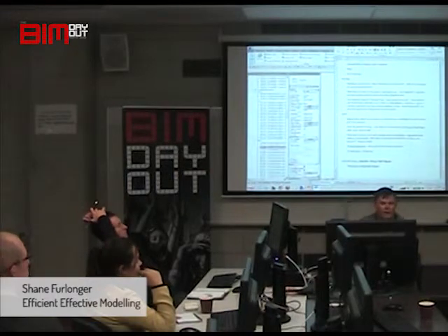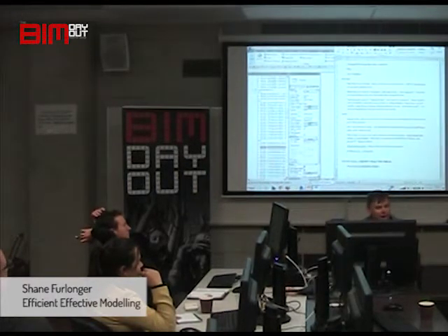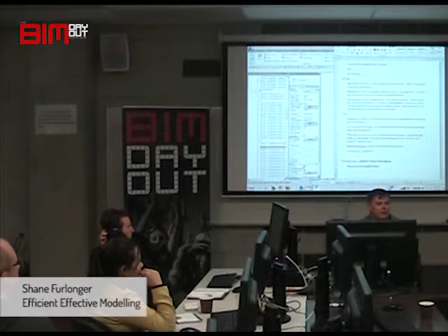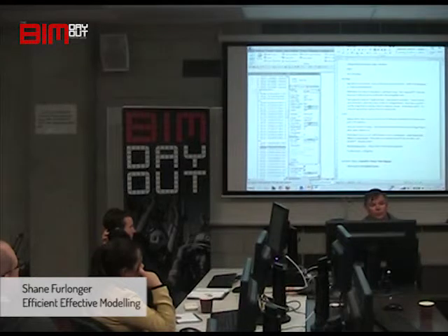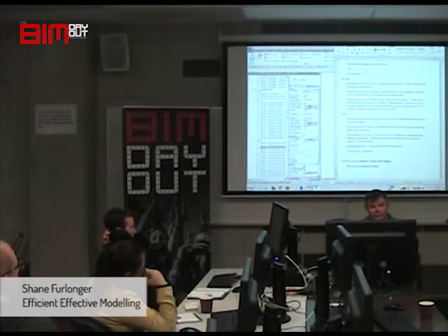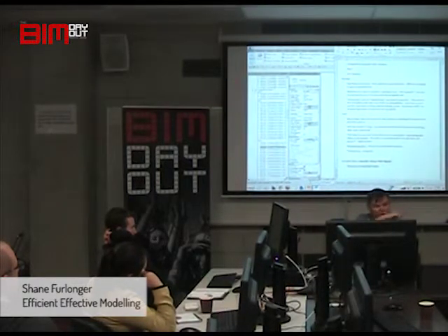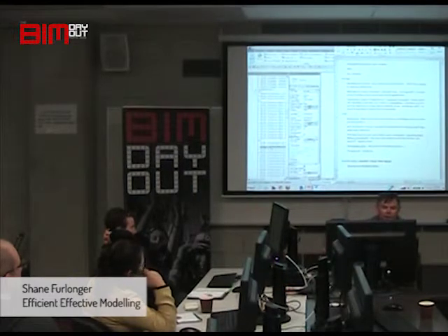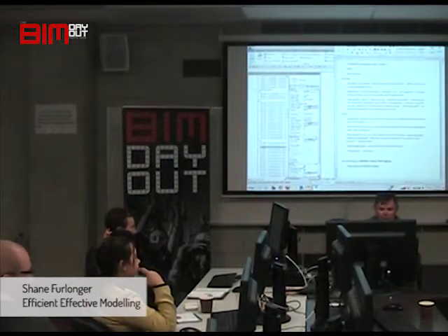Okay. I go level to level and I offset. So when I first put in a slab, I take a guess. My slab's going to be 200, and I will offset the walls 200. It is very easy to go back later and select all those walls. You can just drag through horizontally through your building and filter out everything except walls and change them to the heights you need in one go. If you don't do that, you run into problems.